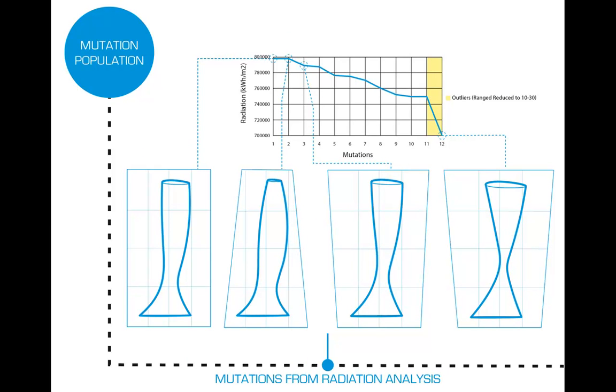The next process was the evolutionary solver, and we were basically asked to run an analysis on the tower and evolve its form to improve based on a constraint. So hence the name, I chose radiation as my constraint to analyze the tower. Using the Galapagos evolutionary solver that Eric mentioned earlier, we were able to transform the tower in multiple ways. The curves that I showed you in the previous slide were used as a genome, or the part of geometry that was going to be manipulated to generate results, and the goal was to minimize radiation.